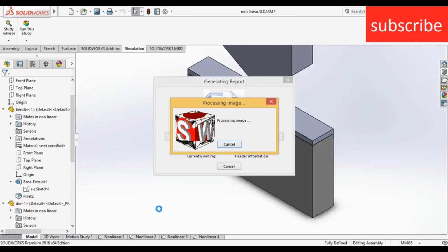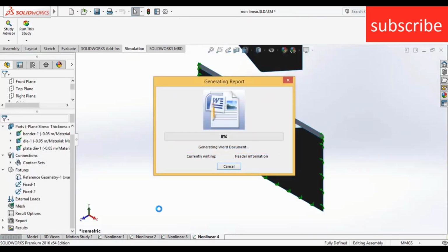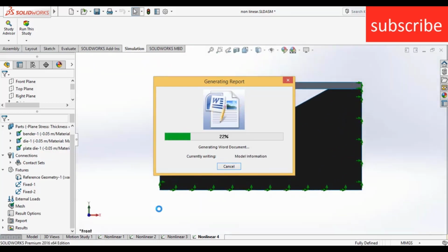While doing reporting, let me tell you what kind of things it will show. It will show what boundary conditions we applied, and what the loads are, what the maximum stress is, what the average stress is, and many other things. If you want to insert particular pictures, hey, I want to do this thing, you can also do that.